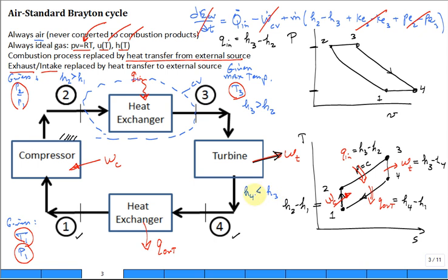It went down. And then you have heat rejection out of that heat exchanger. How about the enthalpy 1 compared to the enthalpy at 4? Which one's greater, 1 or 4? 4 is greater, so H1 is less than H4. True? So if you get those relative magnitudes of the enthalpies, it helps you not make a sign error.